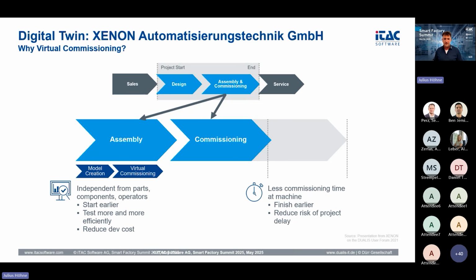So in this video, we usually show how we do the commissioning of a system in a virtual commissioning. There we have a robot, a Stäubli robot, and we have a PLC program. The robot is controlled by the Stäubli robotic suite, and the machine itself is controlled by a real PLC program. And this setup allows us to run individual PLC cycles, so we can test them separately and in combination with the robot.